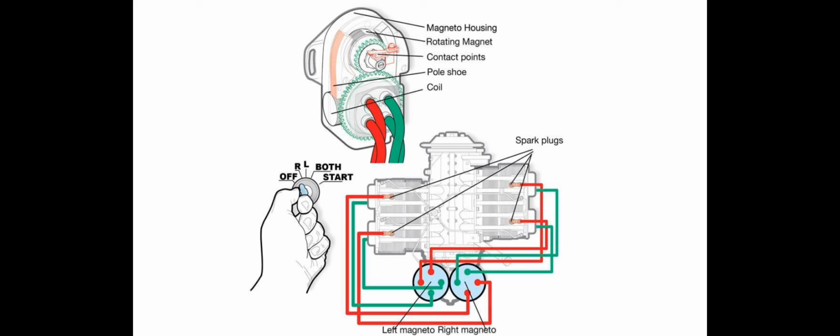How can you tell if a starter commutator is dirty or worn? Excessively noisy starter. What does it mean when the starter relay clicks when the starter switch is placed in the start position? Supply voltage is too low. The relay coil can't fully engage the contact points.